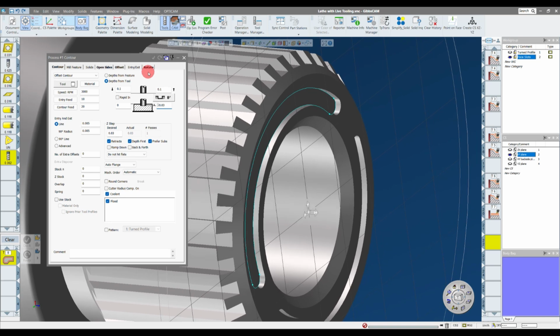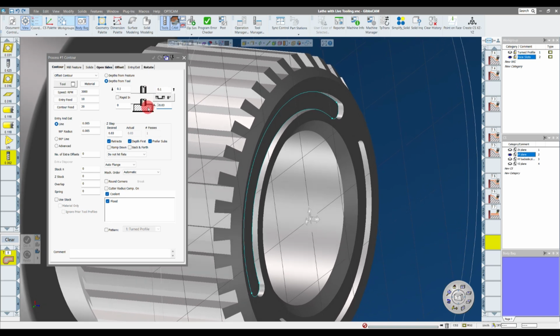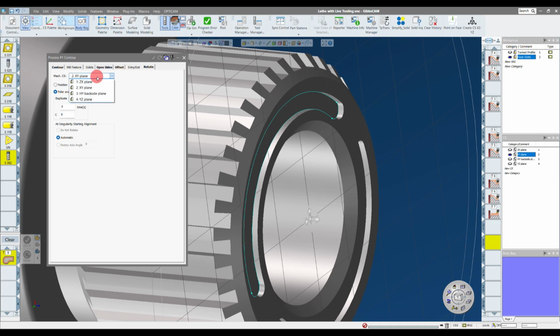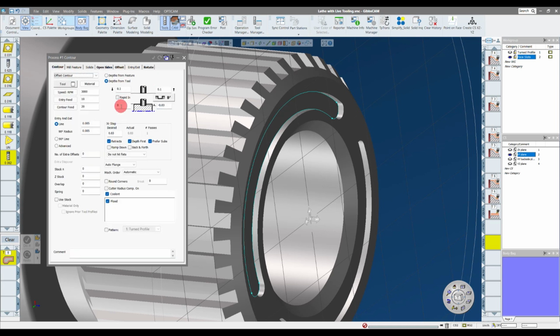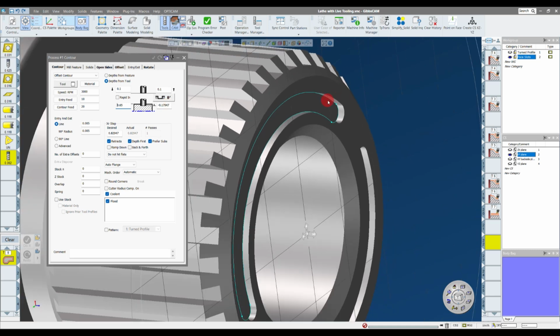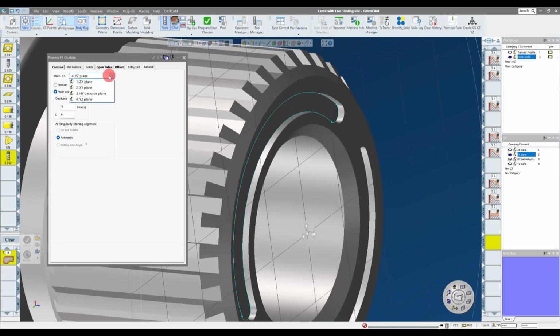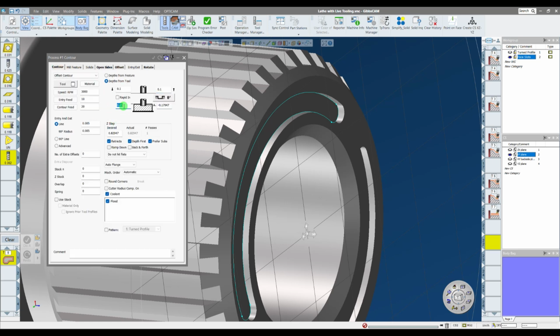Now, I can't advise this enough. You are the brains behind the operation when you're programming and developing process to machine a part. So don't rely on what it gives you if it doesn't make sense. So for instance, if I were in a different coordinate system and I interrogated a feature and the number just didn't make sense, I know that that's not 179 deep. I know that the face of my part isn't 0.65. If these numbers don't make sense when you interrogate them, you want to think about it. Double check your coordinate system. Make sure you're in the appropriate coordinate system. Then when you interrogate for these numbers, it does make sense. Make sure the numbers it gives you make sense.